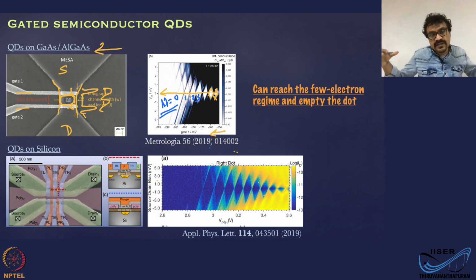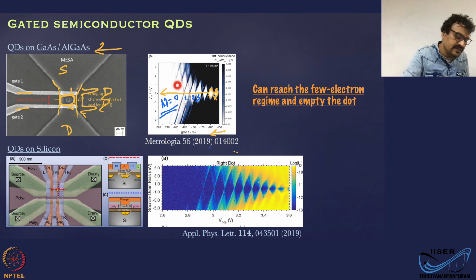So you can take the Coulomb diamond, then you vary or sweep the gate voltage until you don't see any more diamond, or you open up completely. That is a region which is going to look something like this. Then you increase the gate voltage, make it less negative, and you can see that the diamond will start closing.